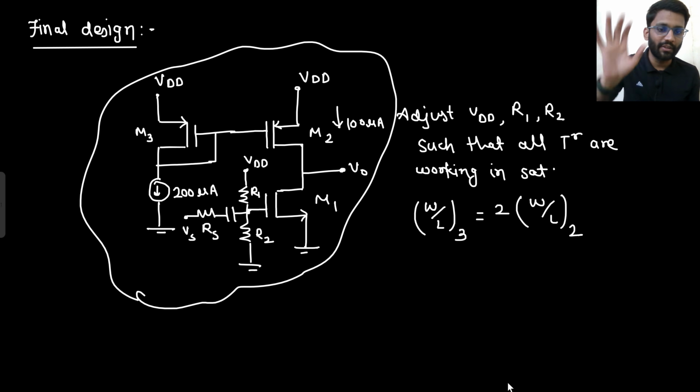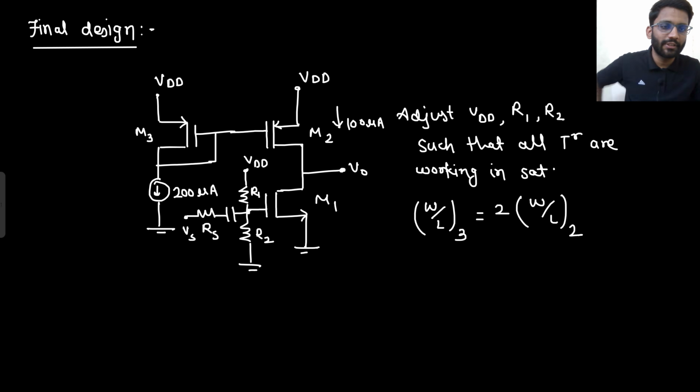So if this question was in front of you and they asked for the small signal gain, what you would understand is that they are using a 100 microampere current source as a load. Now this 100 microampere current source will have an output impedance similar to what M2 is having. So from here, what output impedance do you see? That is R02. So directly you will make R02. You will not even look here because the current is copied here. That's it. Then you will make this M1 and directly write down the final gain.